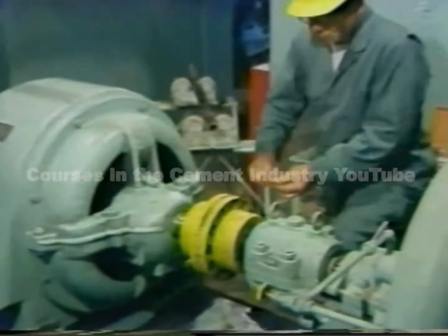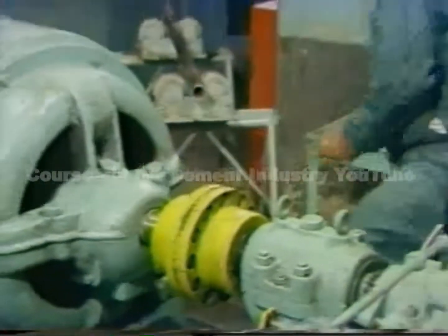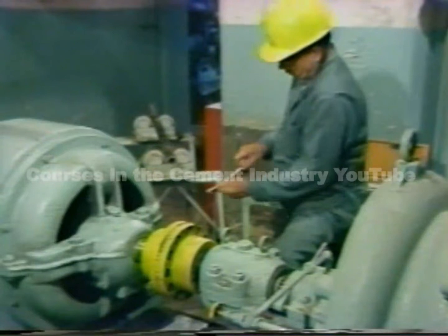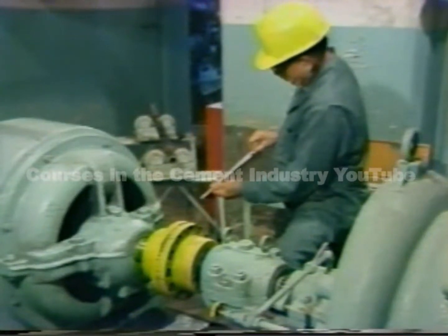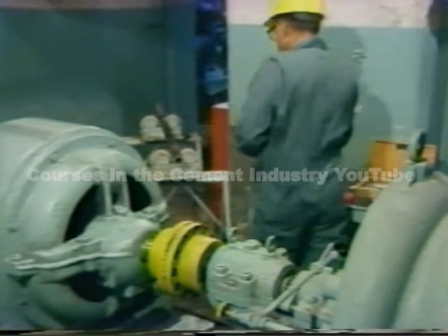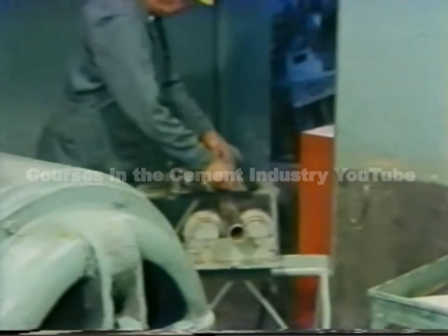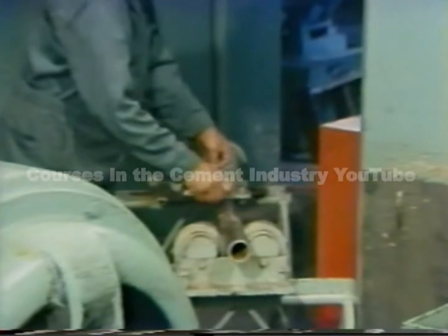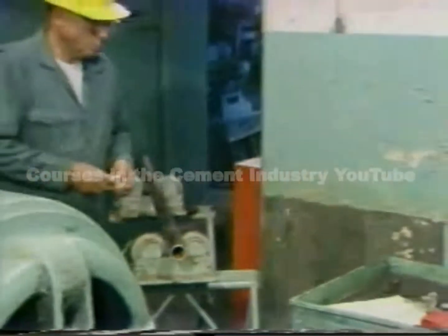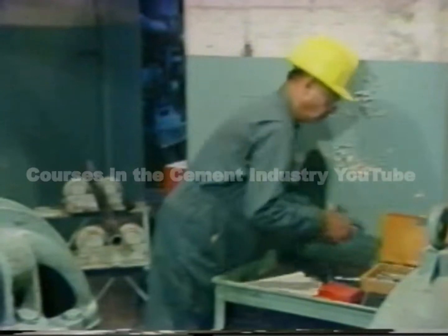Once a good spot is found, a rough measurement of the distance across the coupling is made. This doesn't have to be exact. It'll only be used to determine which rod to use. A measurement of the rod is made so we'll know which one will fit across this coupling. Now, rather than mount the post and bracket on the shaft at this point, a distance is measured off on a pipe that will indicate how far apart the two will be when they're mounted on the machine. That way, the whole dial indicator setup can be mounted on this pipe for the sag check.